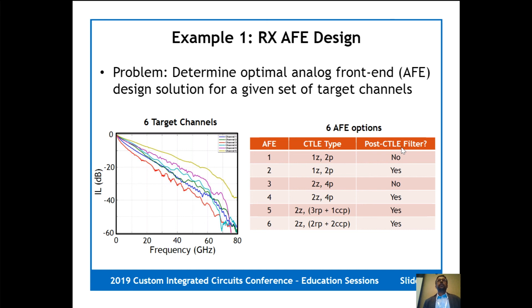So the next one, it's a little more murky, from 56 gigabaud to, if you want, looking at 224 gigabits per second. If you want to stick with PAM4, then that would require 100 gigabaud circuits. I mean, that's an option that is still on the table. I think it's too early to say that that's not doable. The question more is, is it doable at a reasonable power cost? So that's not clear. So that's why there are alternative modulation schemes on the table.